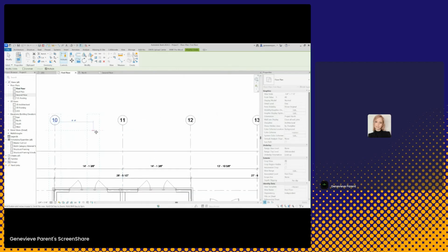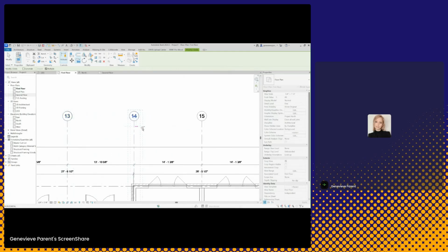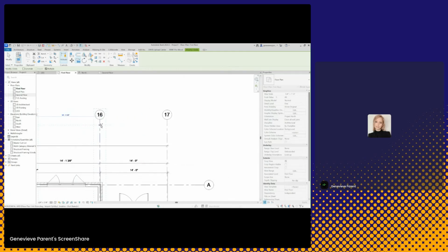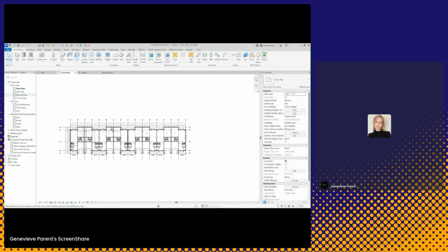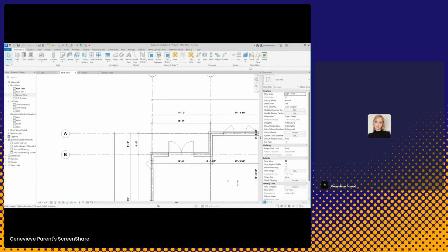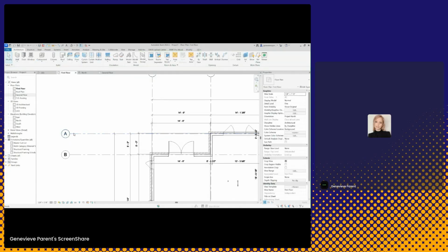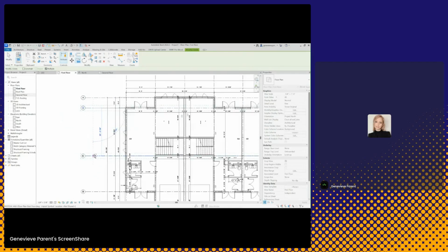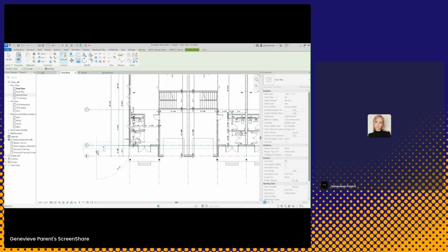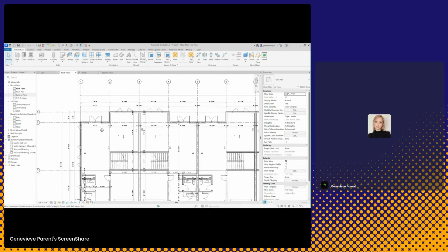It is quite a big building. I'm not going to completely draft the entire building, but I am going to show you guys a couple of neat tricks to make your process go faster. Okay, I have one row done over here. I'm just going to move this over. And I'm going to put in the other row here. I'll re-letter that and copy this one down. There we go. Okay. Now when we start tracing our walls, it's going to be a lot easier.